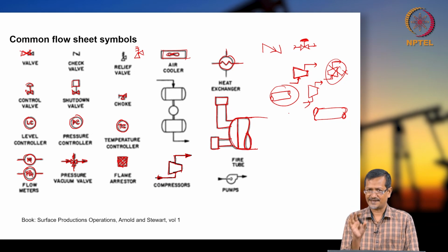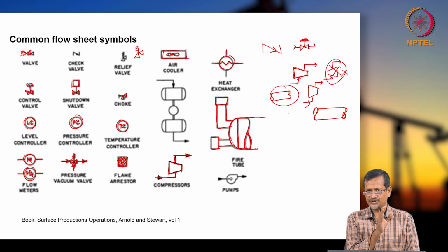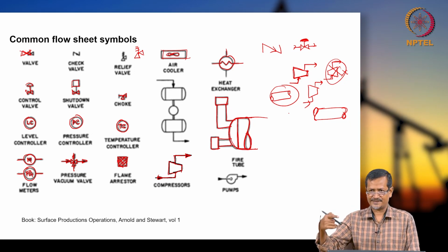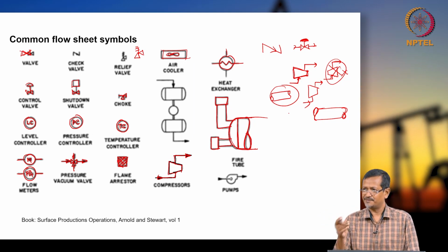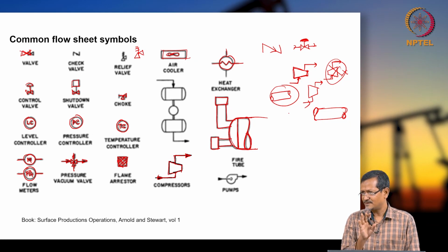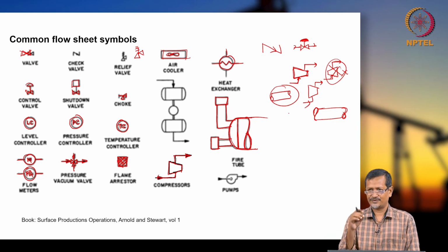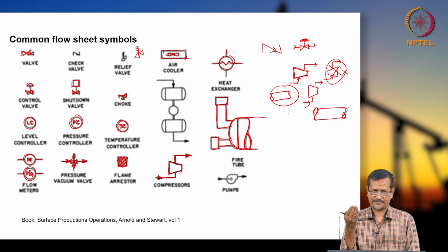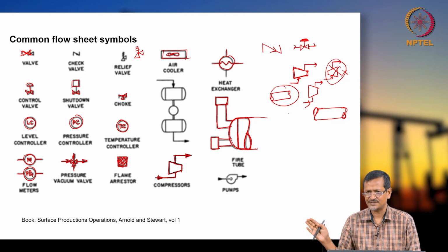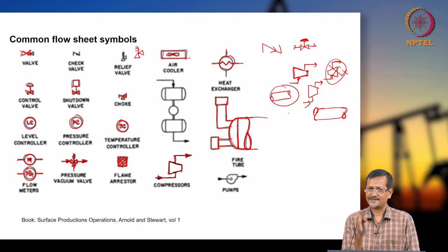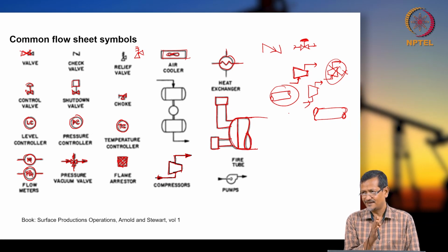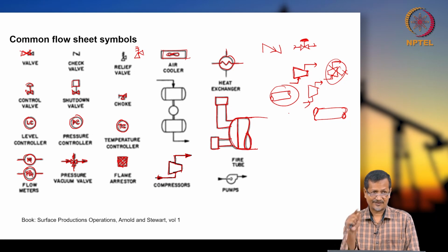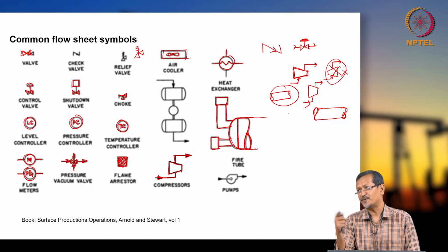So the machine is the same, you are giving energy to fluid using some mechanical means. The reciprocating pump or reciprocating compressor, basically the principle is mechanically the same. If you analyze the fluid mechanics, you will have the basic fluid mechanics equations, everything the same. The only thing is that in a pump it is incompressible, in a compressor it should be compressible actually.